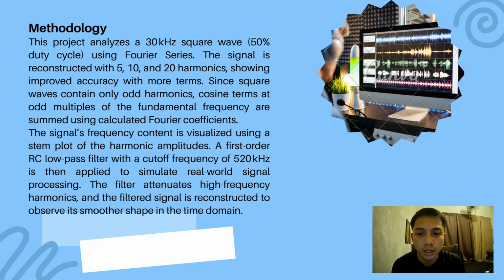A first-order RC low-pass filter with a cutoff frequency of 520 kHz is then applied to simulate real-world signal processing. The filter attenuates high-frequency harmonics, and the filtered signal is reconstructed to observe its smoother shape in the time domain.